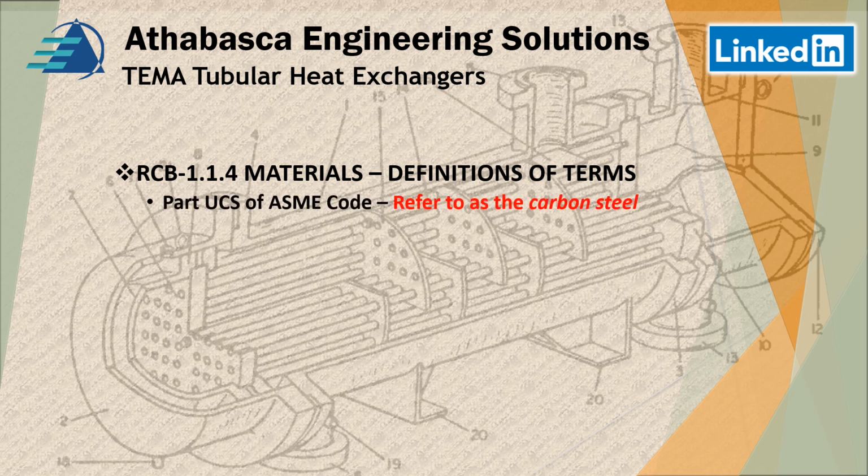So they refer to carbon steel in the TEMA specification. And when they refer to carbon steel, they mean Part UCS of Section 8 Division 1 for what carbon steel means. And they have a list of very specific ASME codes that are used for the materials. Now, metals that are not part of UCS, except for cast iron, and there's specific requirements for that, are referred to as alloys. So you've got the carbon steel group and then alloys.